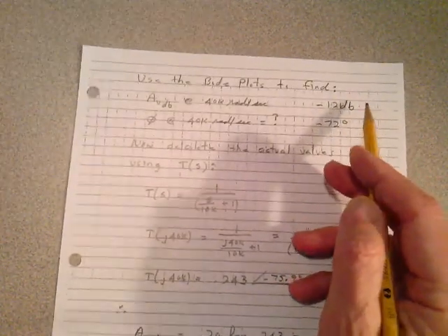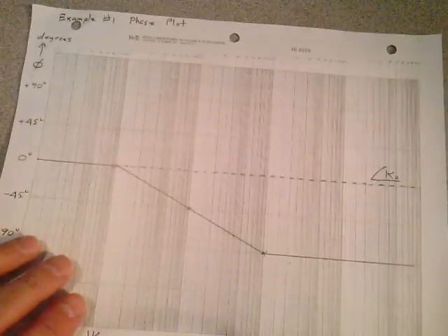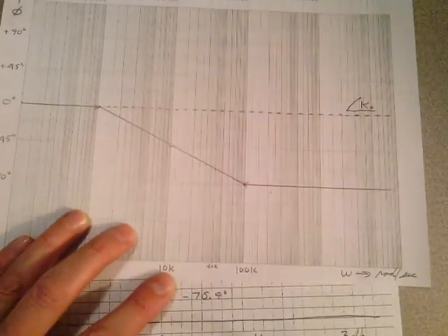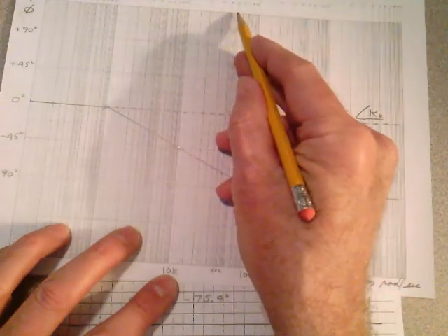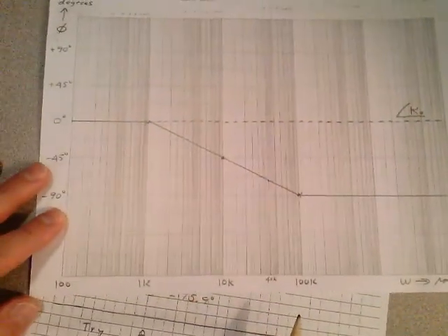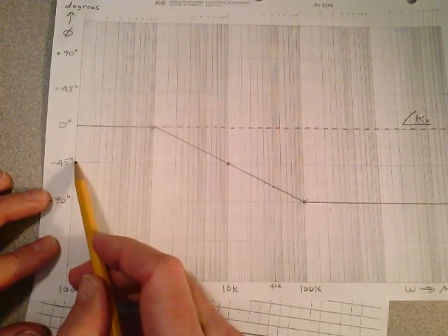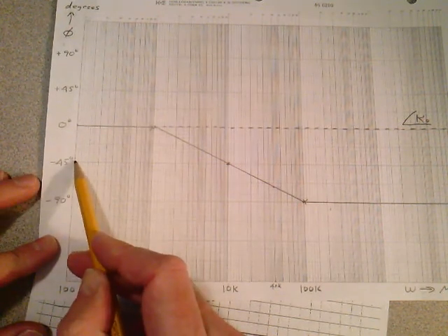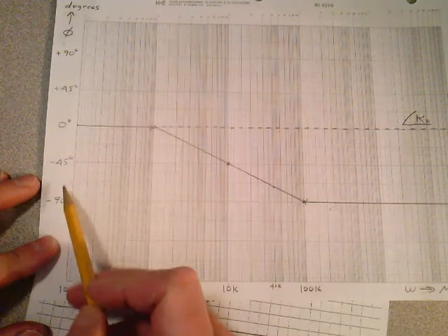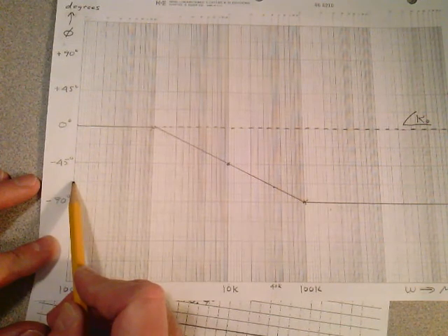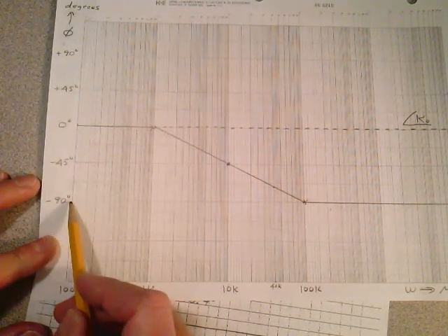And then I want you to take your phase plot. And I want you to look at 40K. 40K is going to be right here. Right there. Again, I have to look up above. That 4 represents 40K up above, and I can come down, and that's the 40K point at that point. And I want to come over, and I want to read the phase angle. Well, the way I have this laid out is there's 10 divisions between 0 and minus 45. This is per inch. And there's 10 divisions here between minus 45 and minus 90. That's the way these all get laid out. So the midpoint is 22.5 degrees between the minus 45 and the minus 90.